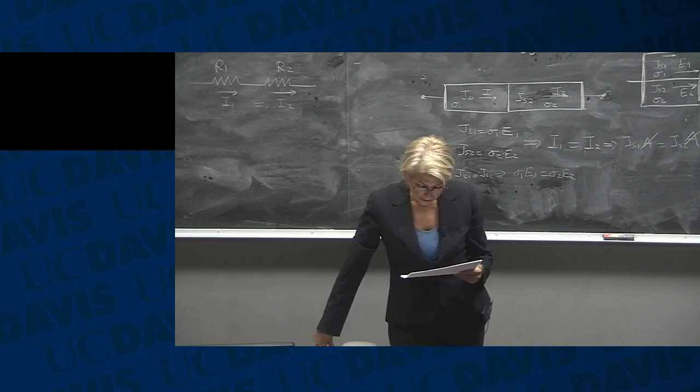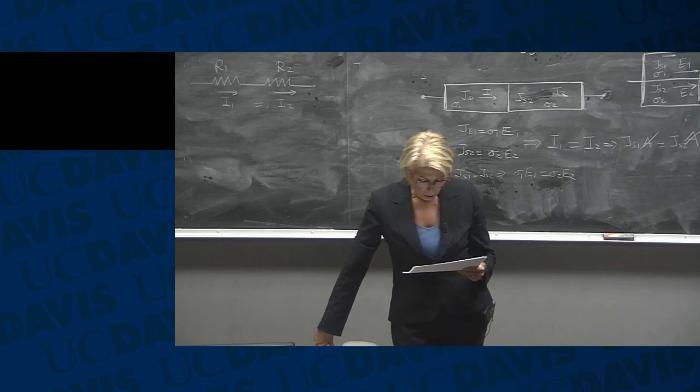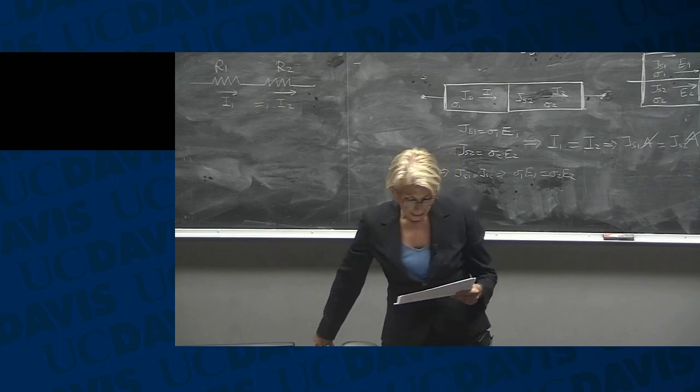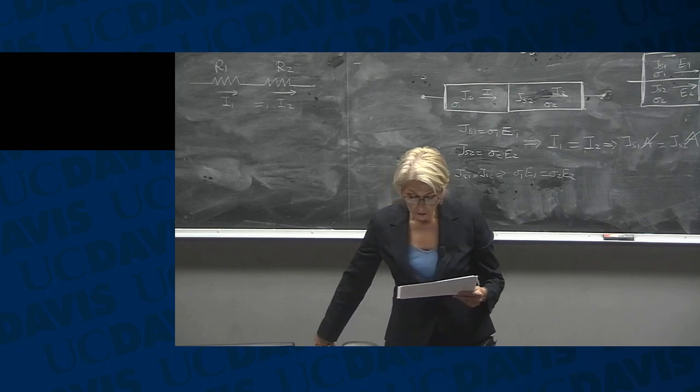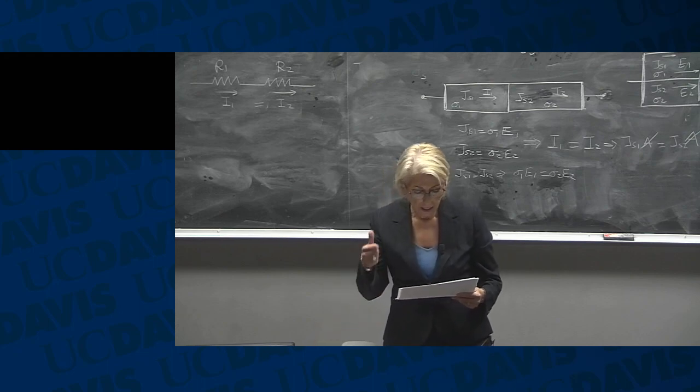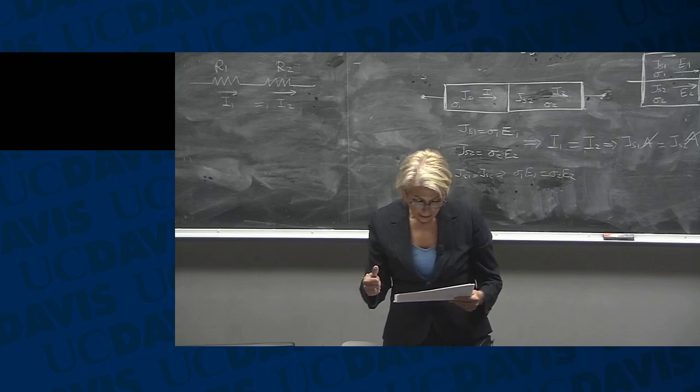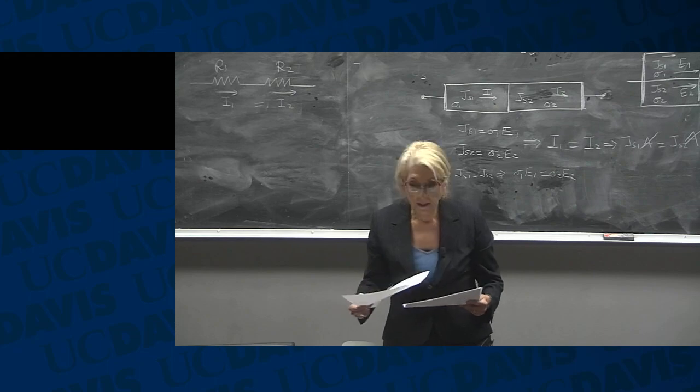Second, find the voltage difference between points 1 and 2. Find the capacitance and compare it to the value the capacitance would have without the dielectric. You assume that Q, A, and H are given, as well as the radius of the inner dielectric rod and the relative dielectric constant.